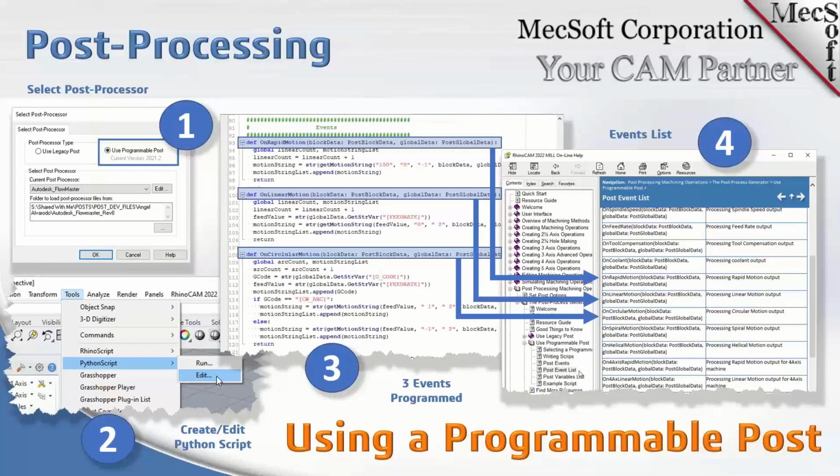For instance, on spindle speed is an event. Whenever in the feeds and speeds dialog you set up a spindle speed, it's written out to the toolpath. And as the system is posting, when it hits that spindle speed line in the toolpath, it'll trigger that event. Then, in your Python script, you can handle that event in any way you want. That's what the item labeled number 3 displays.